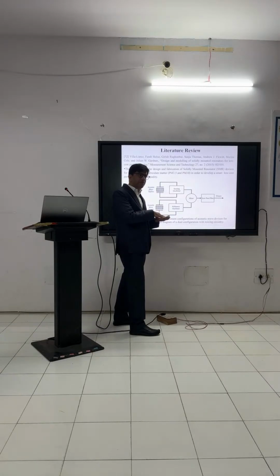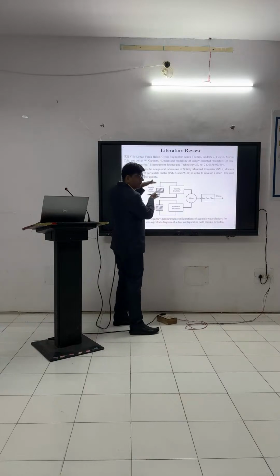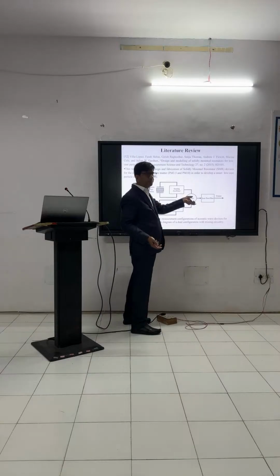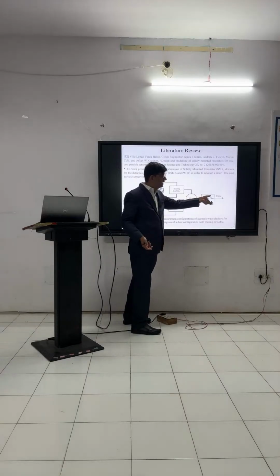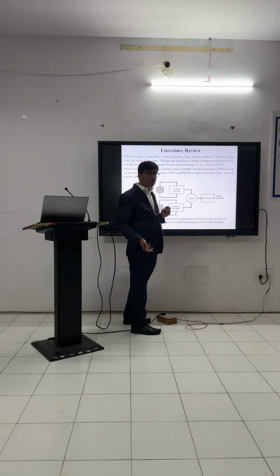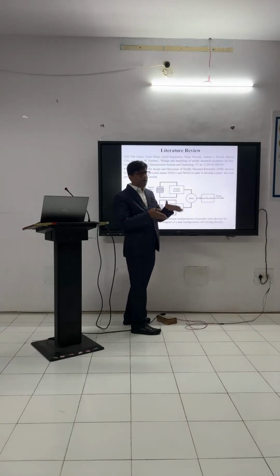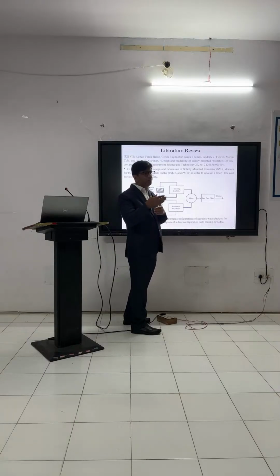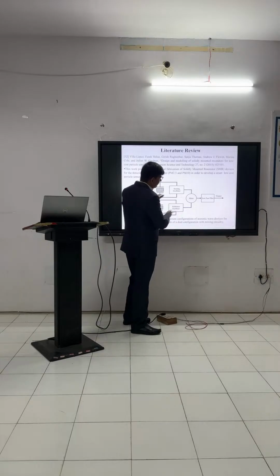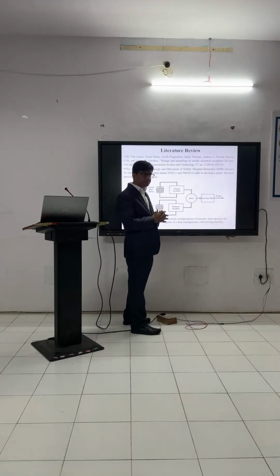Due to this mass loading, my resonant frequency shifts down, and that's why we have an increased delay, which we can measure with the help of the mixer, and we can read that in the form of voltage. So we can find out how much sensing we have at what level of gas, maybe PPT, PPB or PPM, whatever the level, we can easily measure this sensing.